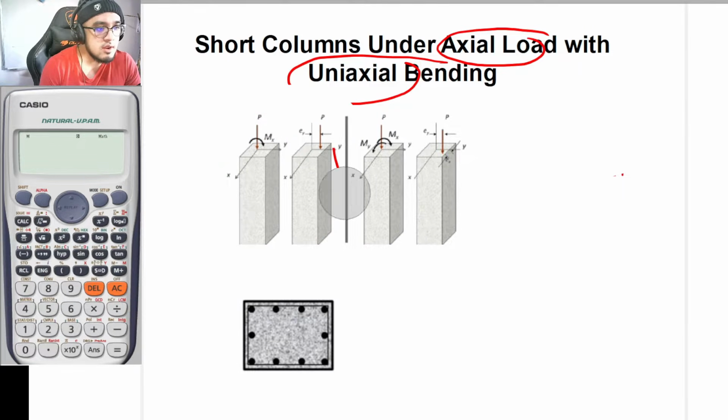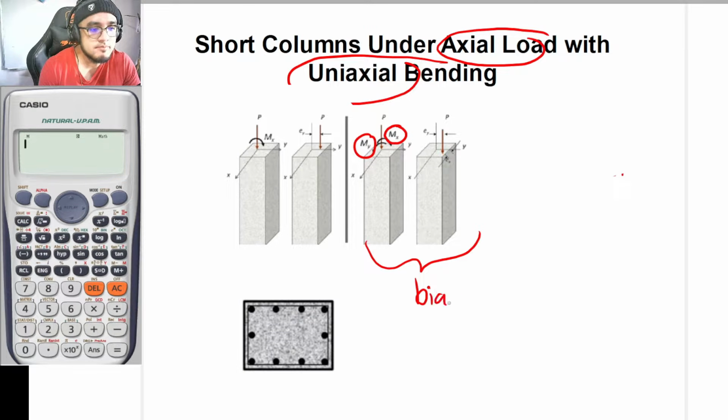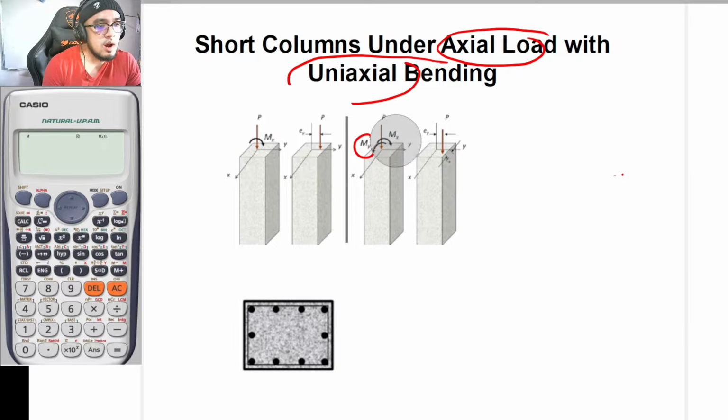And as you can see on your right, in this photo, by the way, guys, I got this photo from structural.org. Proceeding, as you can see, we have two moments here: your Mx and your My. So it means that you would be bending about the x-axis and about the y-axis. Since it is bending in two axes, this is what you would be calling biaxial bending.